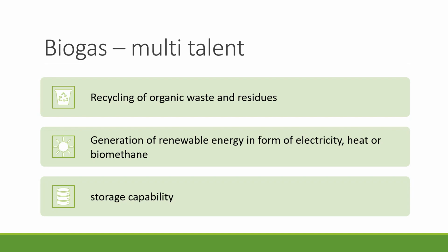A big advantage over solar and wind energy is the capability of storage of biogas. So we can store biogas. We are currently working on projects for customers in the food industry, and they are working 14 to 16 hours per day. That means in this time they have a high requirement for energy, and then we have the night, where the energy demand reduces, and in this phase we are storing the generated biogas, because we have a process which you can't stop. We are storing the biogas, and this stored biogas is used during the day.